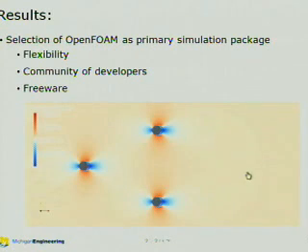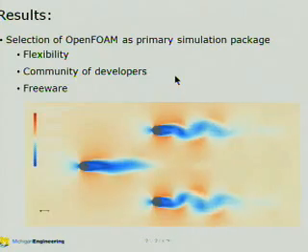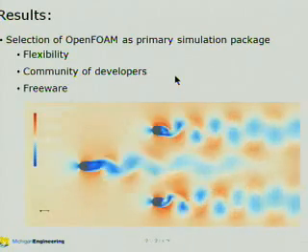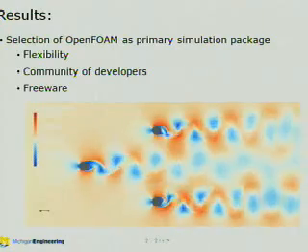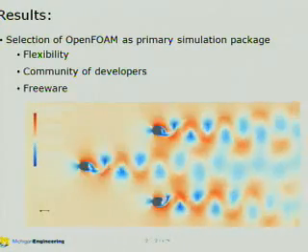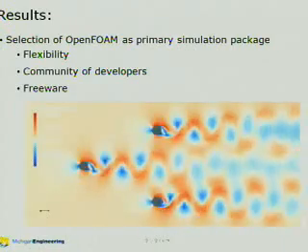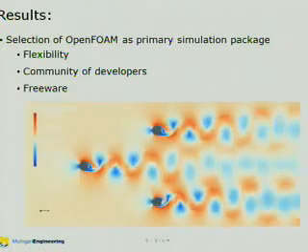This is a 3-cylinder setup where the cylinders are in a triangle and are separated by 8 diameters. Again, the flow domain has identical properties as before. This is Reynolds number of 10,000. The flow comes in from left to right. As you can see here, the leading cylinder has much lesser effect on the 2 aft cylinders, as all of the cylinders obtain relatively disturbance-free inlet flow.